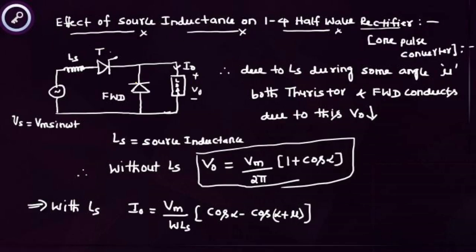Next, what is the effect of source inductance on a single phase half wave rectifier? In a single phase half wave rectifier also the average output voltage is reduced. Then without source inductance, this is the average output voltage, friends.